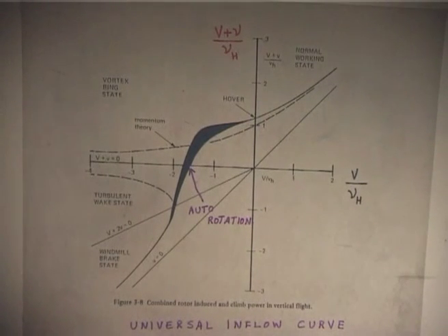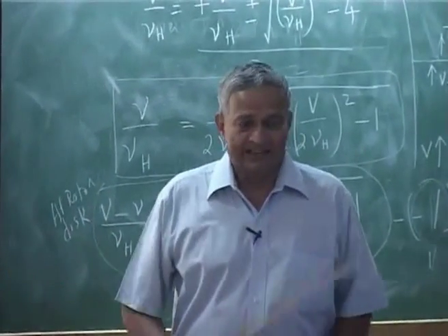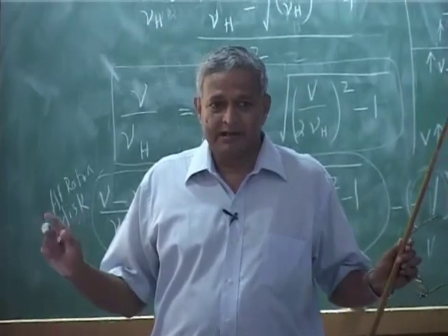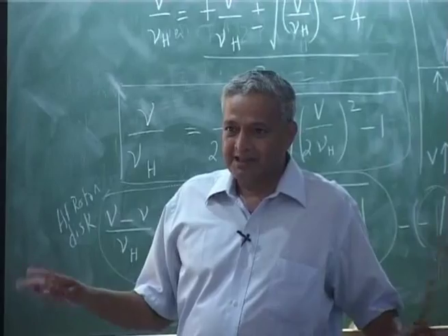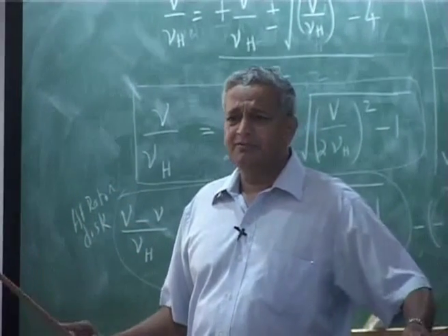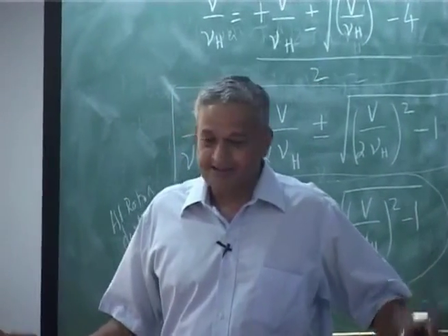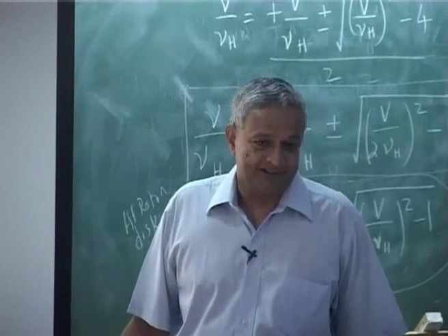We will come back again and show how these two are plotted, climb, descent. Then you will see, oh, this is what the whole thing is about in terms of inflow curve for climb and descent. And then please, it is non-dimensionalized so that it is applicable for any rotor. Okay. And this is what is used for auto rotation evaluation. All right.